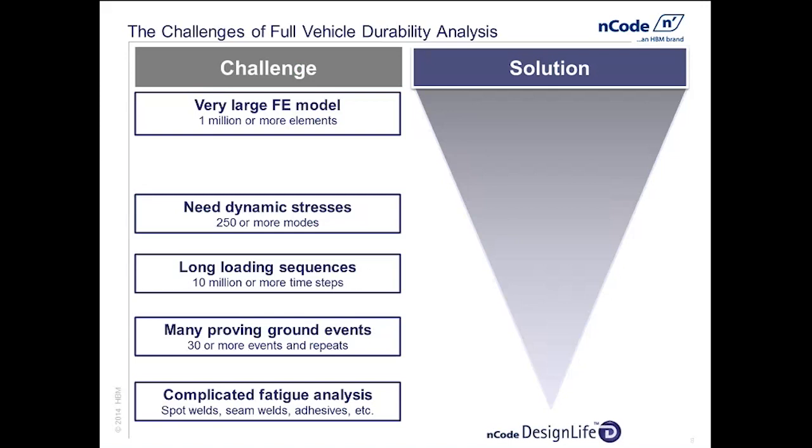A lot of these structures, full vehicles, large structures and so on, oil platforms, vehicles, airframes and so on, can behave dynamically, which means then we need to be able to look at, say, dynamic stresses in FEA, a dynamic solution. That can take some time. So how can we efficiently use FEA and dynamics together, and then do the fatigue calculation accounting for that dynamics? We'll look at that in just a minute as well.